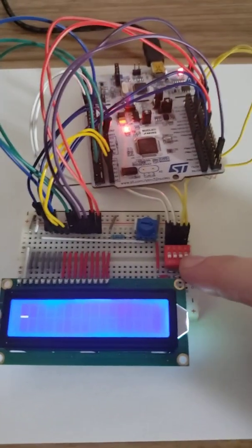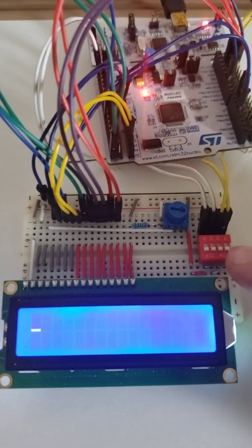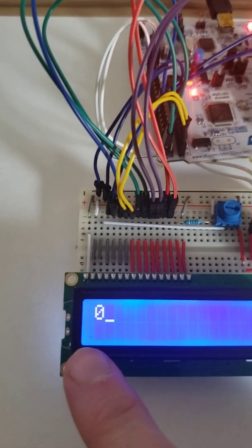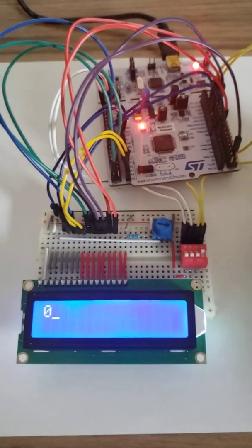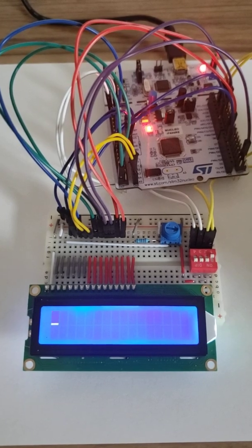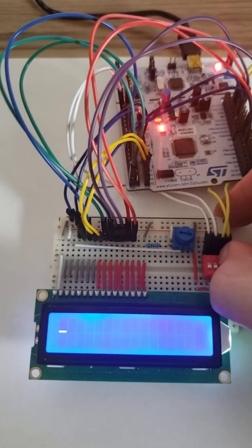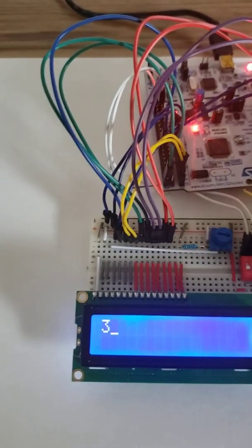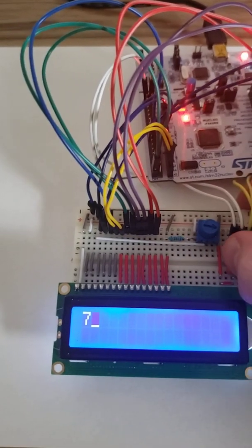Currently we have all 4 of our switches in the 0 position, so it's 0, 0, 0, 0, which is going to output on the lookup table A0. You flip up the first one, which is going to give us a 1 after 2 seconds. It'll display a 1. Then you can try this with 3. You put up another one, you'll get 7. Put up another one, you should get F.